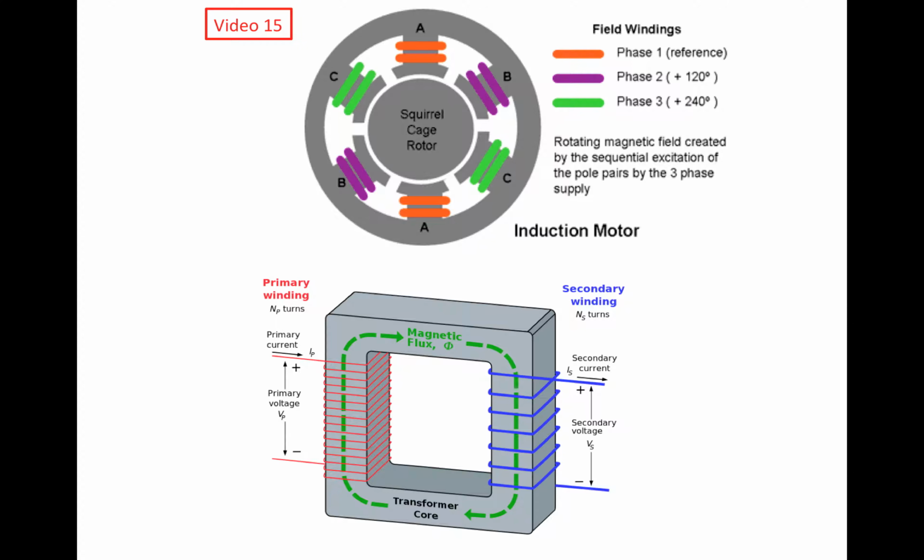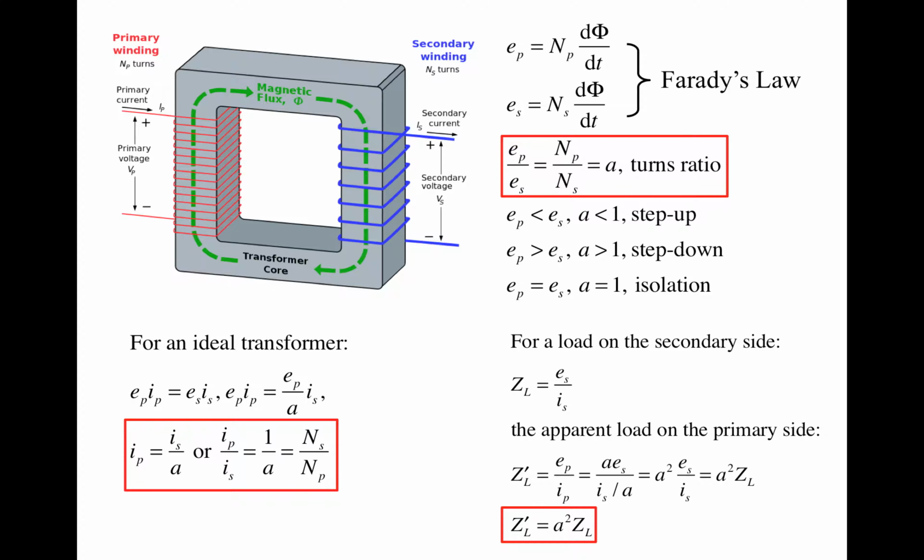And that's the approach that we're going to take in the following videos. So there are three fundamental relations for the ideal transformer. The meaning of the word ideal will become clear when we try to incorporate those non-ideal losses into the equivalent circuit. But for now, let's just consider the so-called ideal transformer.